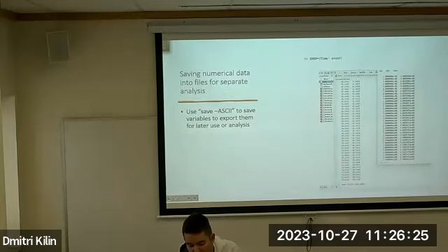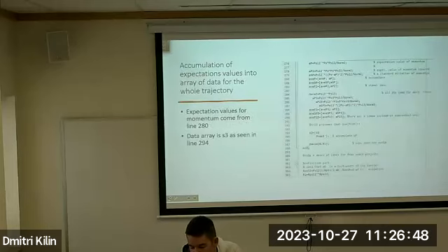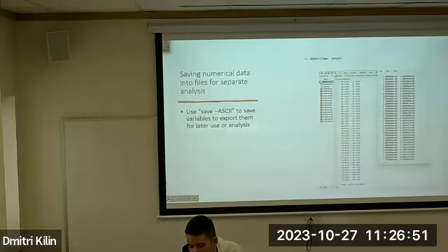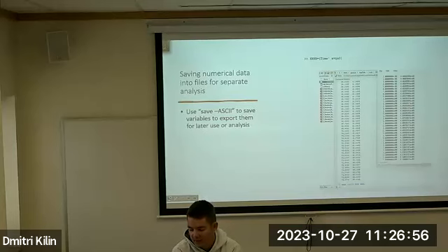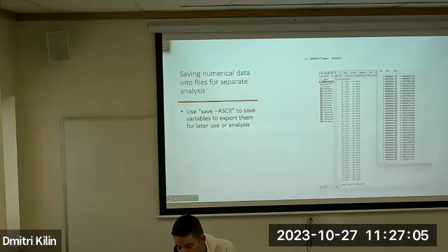The biggest thing from this whole part is saving values for future reference. The command is just save -ASCII. Running this, I saved under an arbitrary variable time and average of S3, which is left out on this slide, but I saved it. You can then export that to any graphing software, or in my case, I just opened it in Notepad. You can really open that and work with it in any software of your choice. That's the biggest thing.